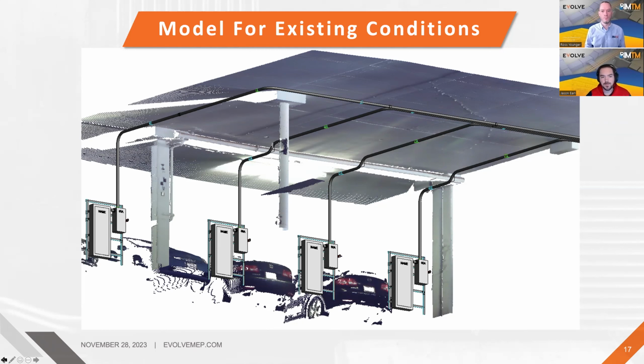And so in here, what I've done is I've shown in Revit, we took a point cloud and we modeled up these EV charging stations. We modeled the conduit that's going to go back to some equipment that's going to feed these. And the real advantage of scan to BIM, in my mind, is twofold, and part of it depends on who it is. But from the contractor's perspective, it's really about that interruption and downtime, right? So bringing that to the minimum amount possible.